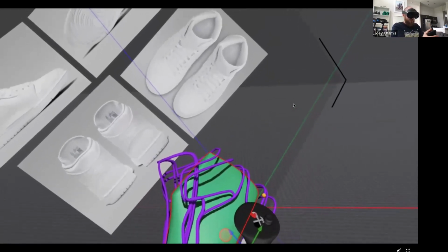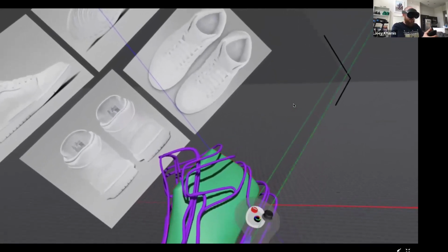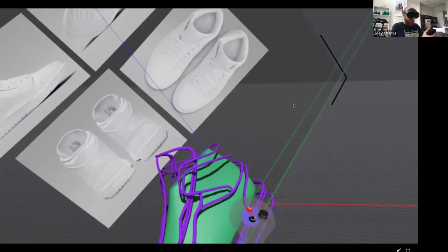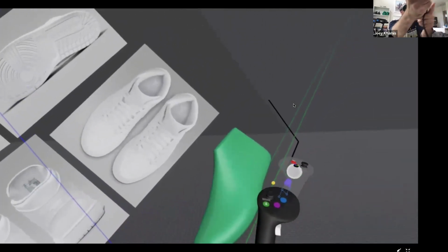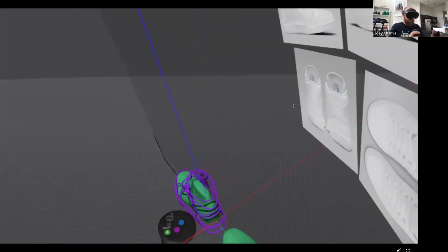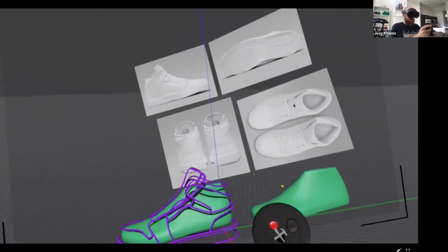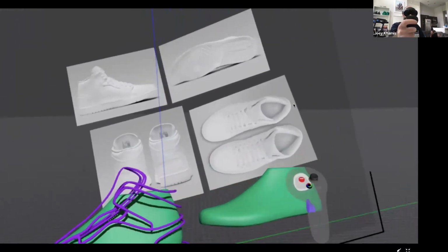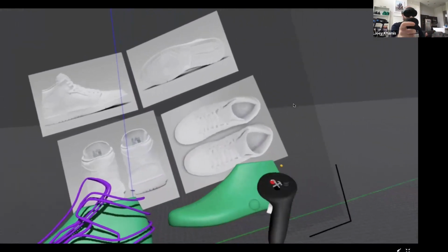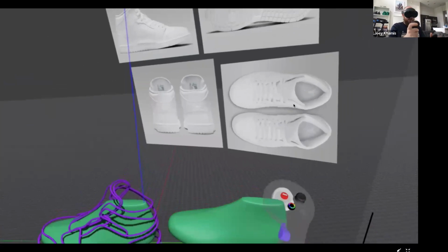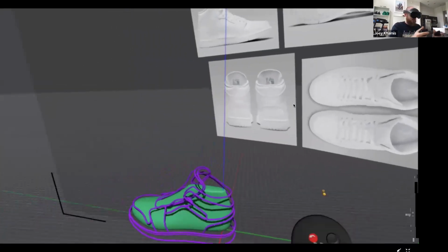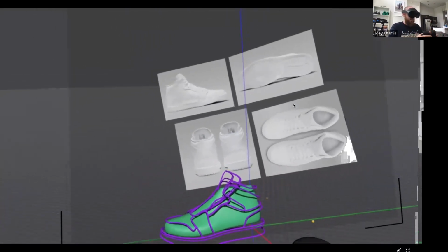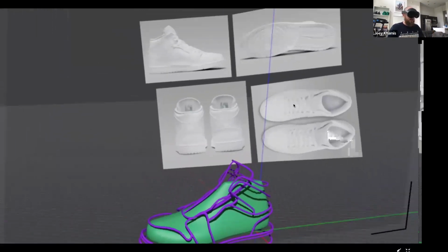So I'm going to do that: grab with the middle finger and then duplicate with the pointer finger, and then I can drag it along this axis. And now I have another copy of it, and it's only shifted over and not just floating over here, where you don't know if it's sitting properly, at a wrong angle, or not on this mirror plane how I wanted it. So that's just a little trick that comes in handy.